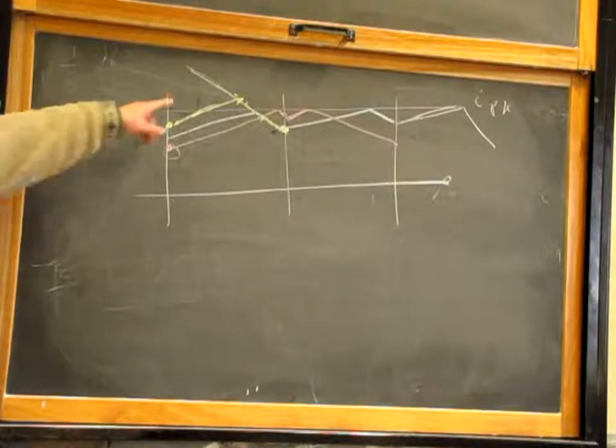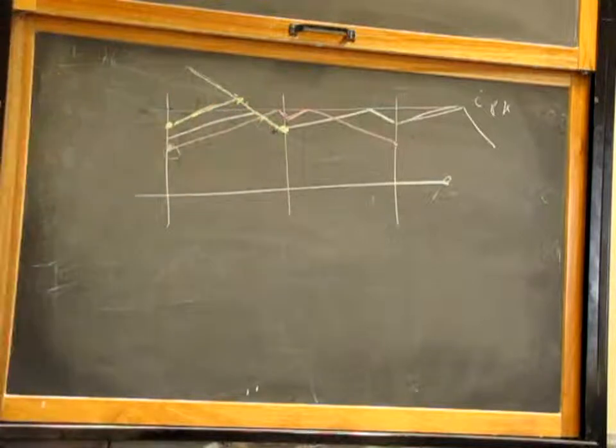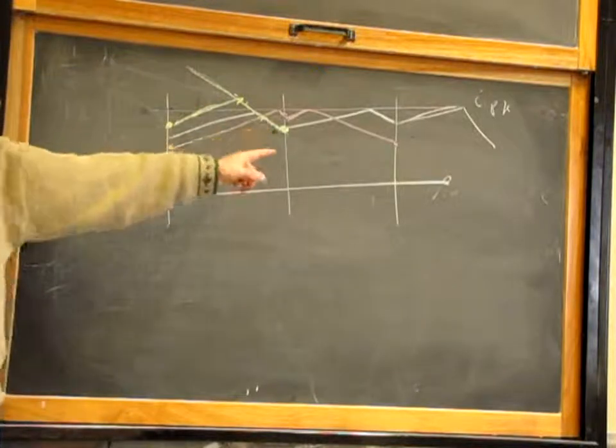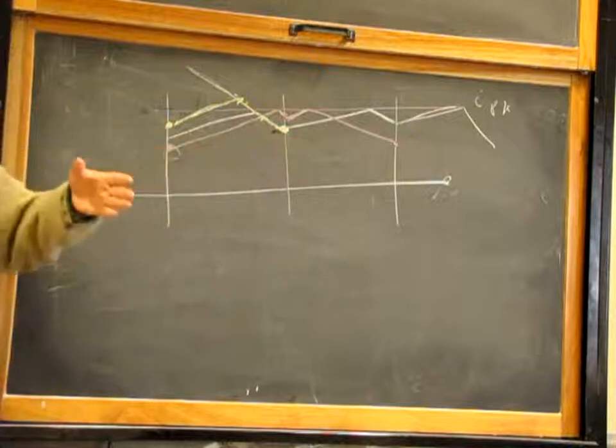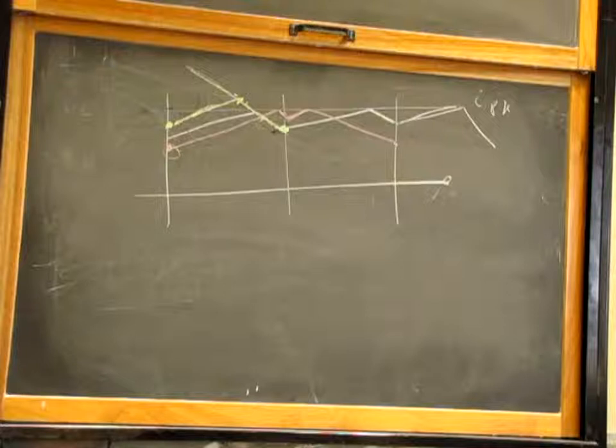And this is the case. Quite often when you design a high-power buck-derived converter, your duty cycle is for sure larger than 50%. So this is something that you really need. What's the slope or the compensation ramp you need to end each cycle exactly at the right value to kill your subharmonic instability exactly in one cycle?